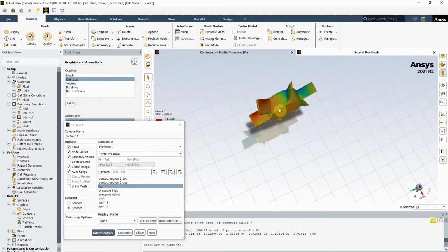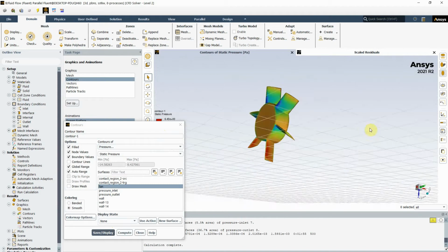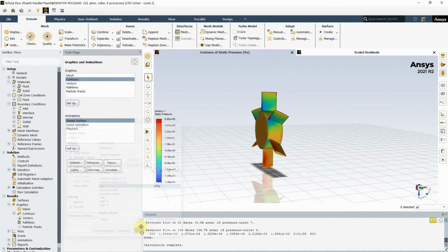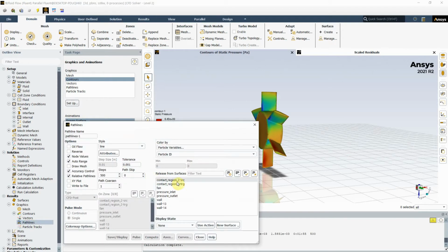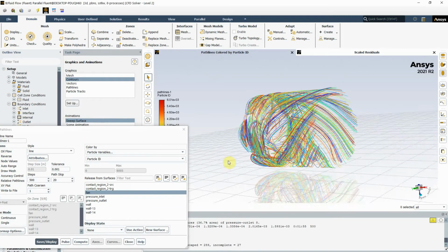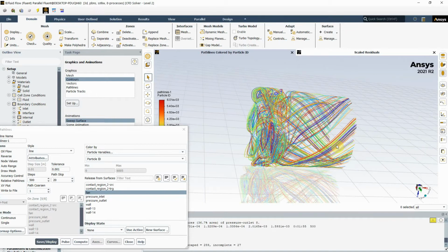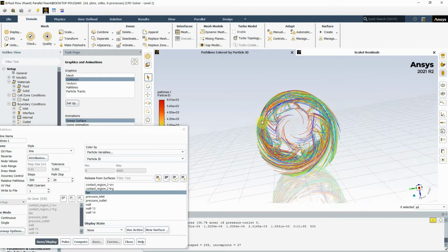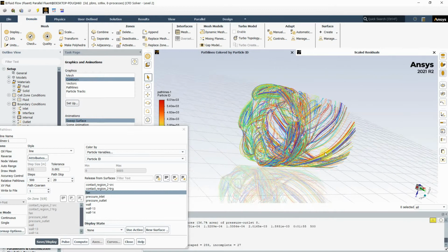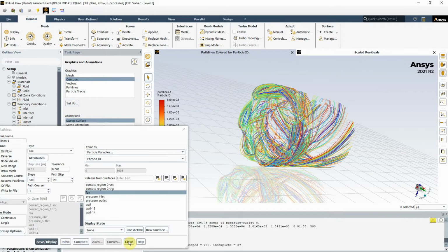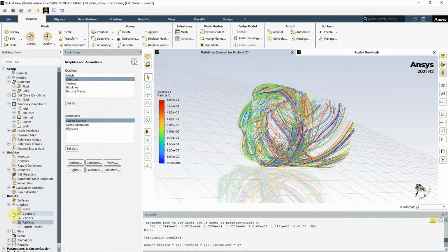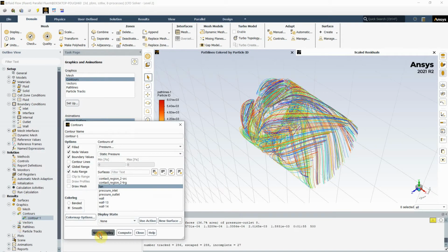Now, obviously, we want to make sure that this is actually rotating and doing what it's supposed to do. One of the best ways to double check that it is working is by looking at the path lines. By selecting the path here and then skipping by 20, pressing save and display, you should be able to see that there's an actual rotation taking place. And as you can see here, there is definitely rotation taking place. That gives you confidence that the actual RPM fan is rotating.